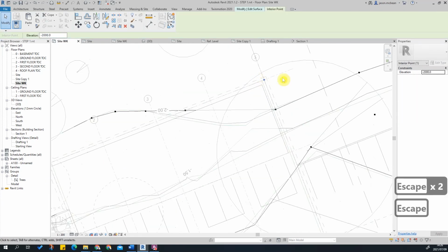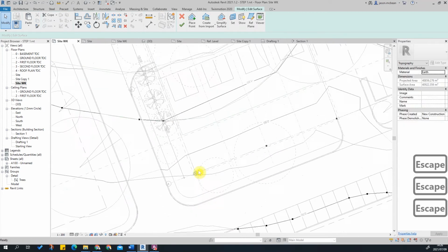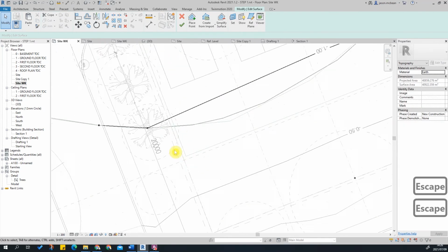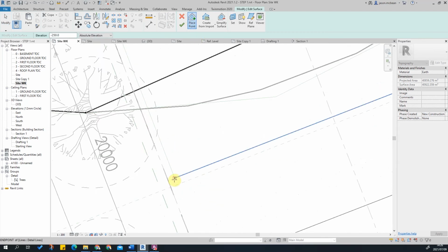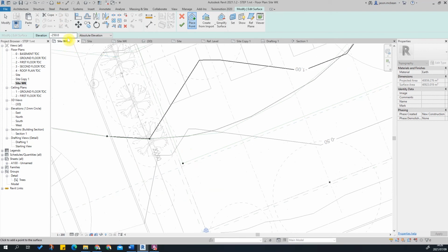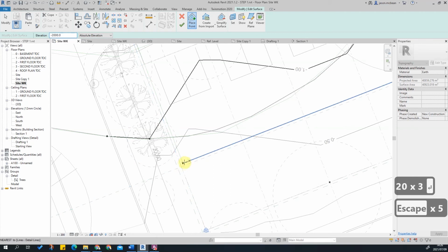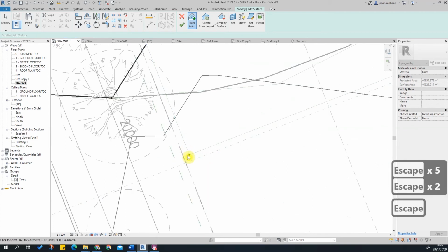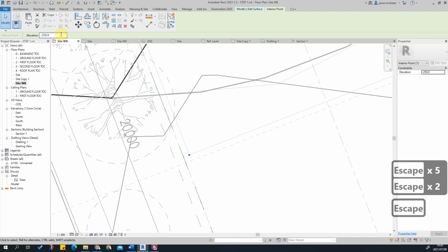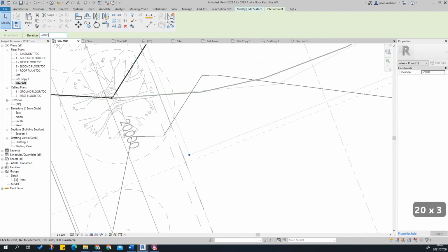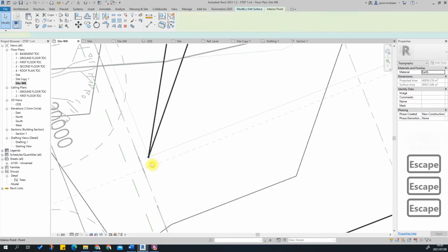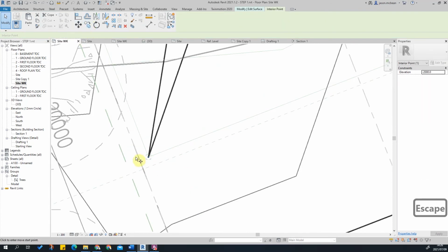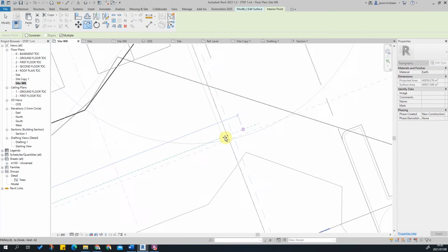Okay, so this -2 meters. We are going to use the -2 meters here as well. Okay, this is going to start looking a bit strange, but it will start fixing itself. So our basement starts there. Yeah, that's -2 meters, sorry, 2000. So let's just select this point. Cancel. Select this point. -2000. It's going to dramatically change. You can see it's having a massive impact. So I'm going to grab this, copy. So from there, I'm going to copy it to there. Okay.